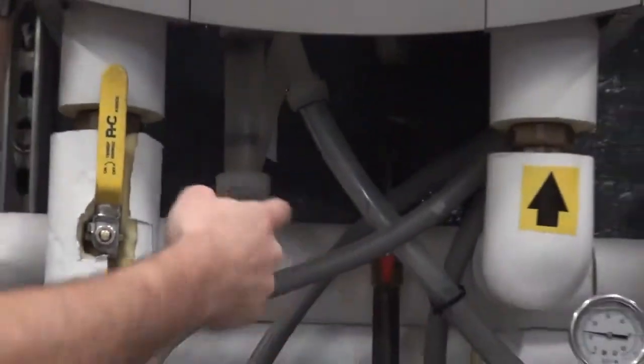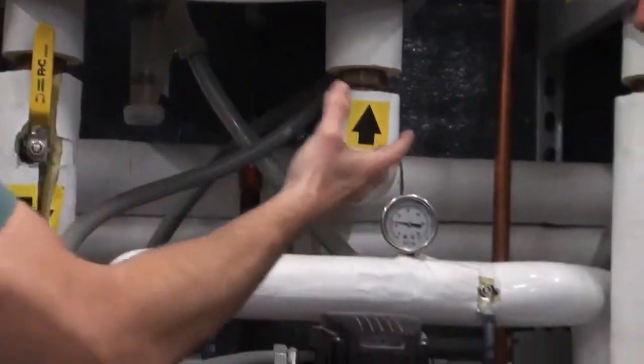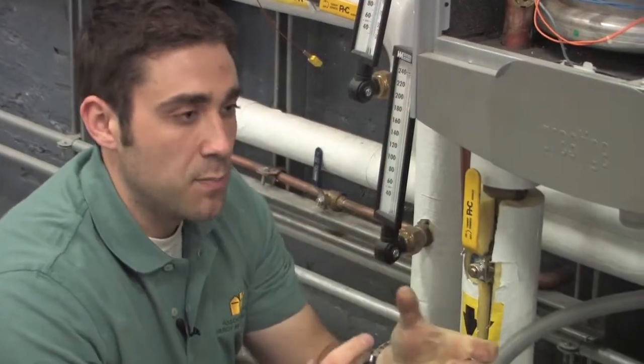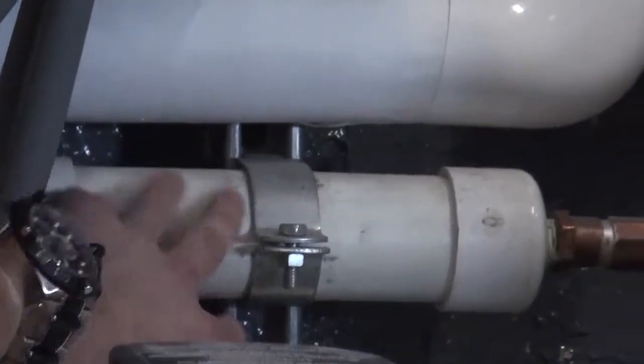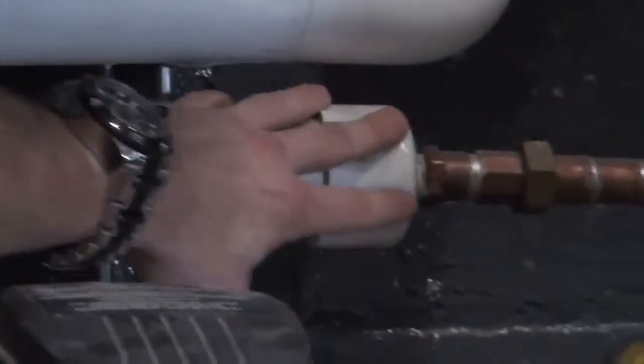So what we do is we actually send it through a neutralization kit, which is a simple little PVC pipe. It's a PVC pipe filled with lime chips, and that actually neutralizes the acidic condensate, and it goes into the draining system as, you know, a non-acid.